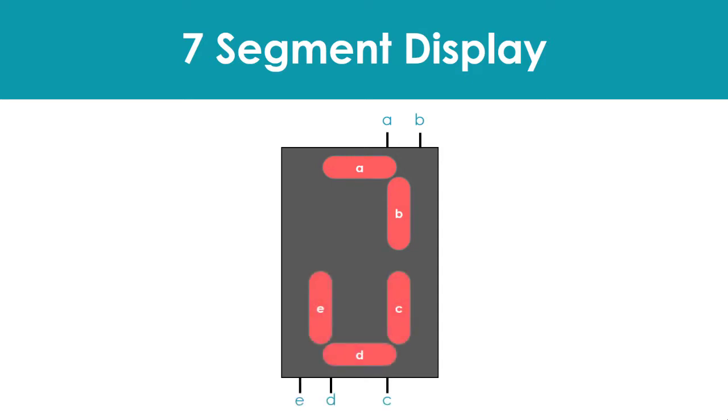Each one of the 7 LEDs in the display is given a positional segment with one of its connection pins being brought straight out of the rectangular plastic package. These individual LED pins are labeled from A through G, representing each individual LED. The other pins are connected together and wired to form a common pin.